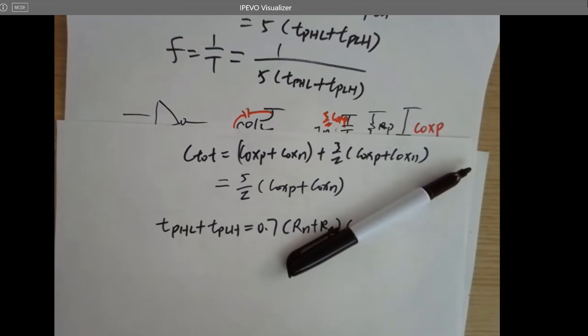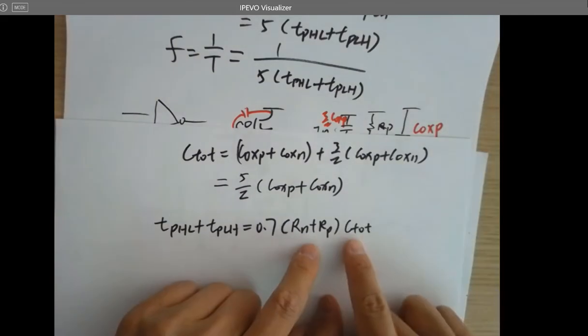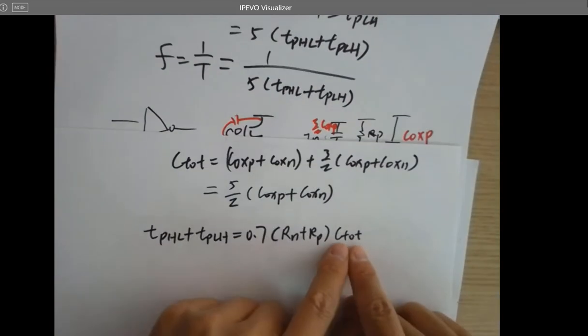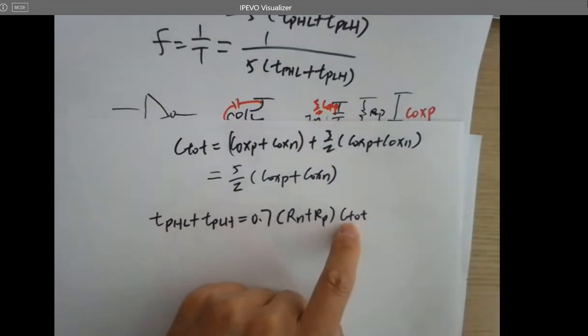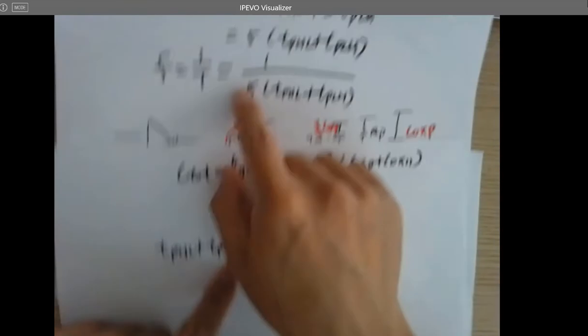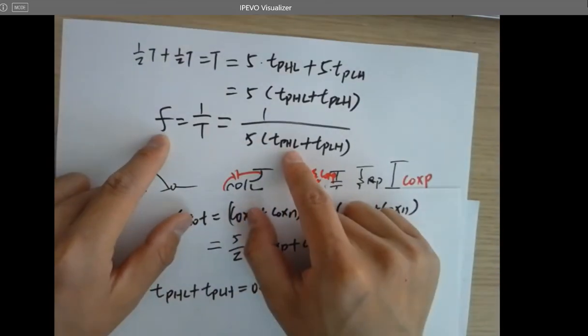The ring oscillator can be used to provide really fast clock signal in digital circuits. Super fast, especially for what I have seen in my graduate school in the publications they use, because you can imagine, right? This can be tiny, especially for the small technologies, and the frequency can be in gigahertz, multi-gigahertz.